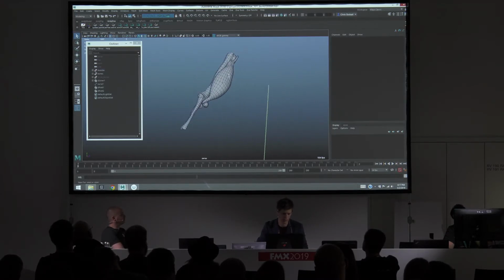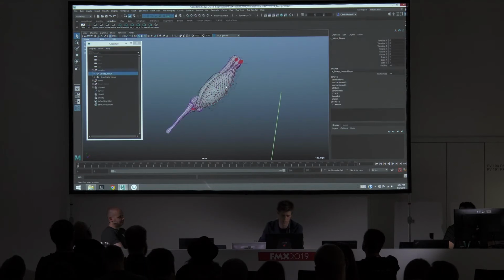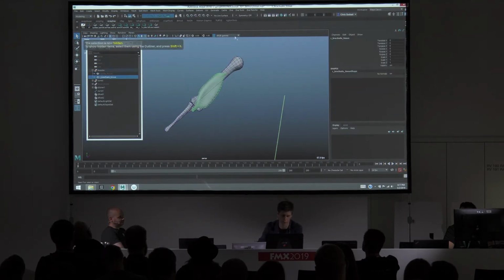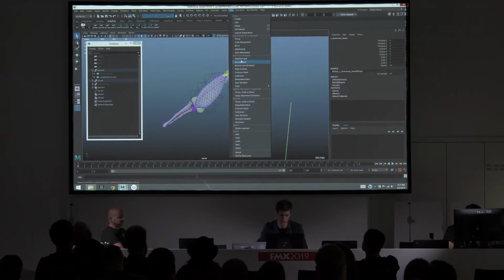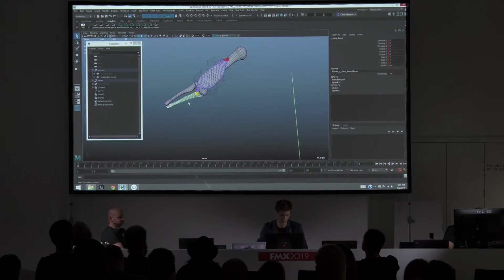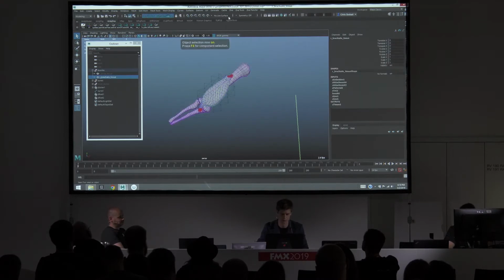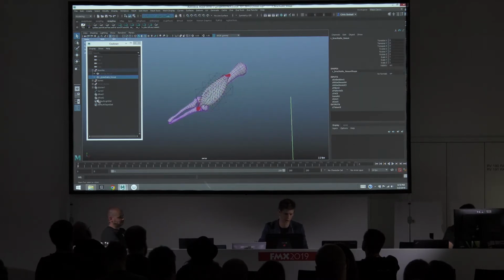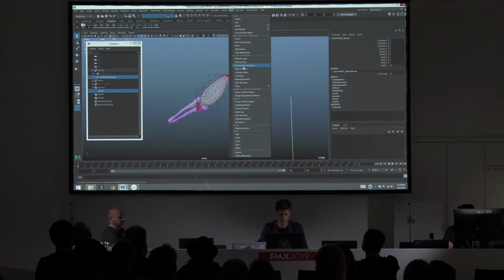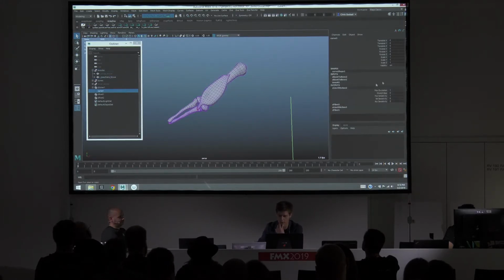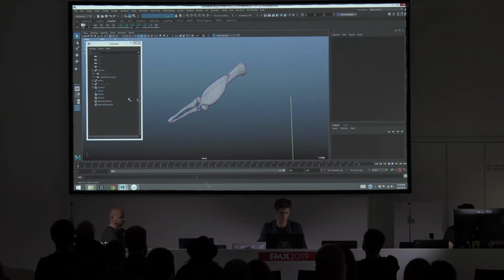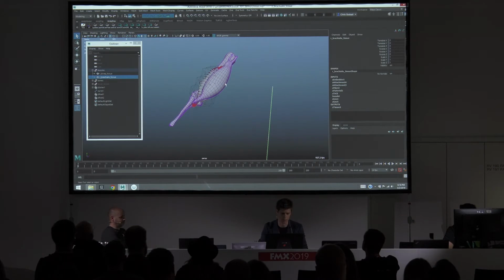Cool. So the next thing I'm going to do is add another muscle. So add the brachialis. And then just to sort of illustrate how quick it is to bash through this stuff, you can sort of just add the tissue, do the origins and insertions. Attachment. And then I'm going to make a fiber on that. Add some fiber. And I'm going to use that same curve to drive it. So line of action. So we have a second line of action node now. I'm going to make it 4 times more sensitive. And now that muscle's also in the system. So it's doing its thing.